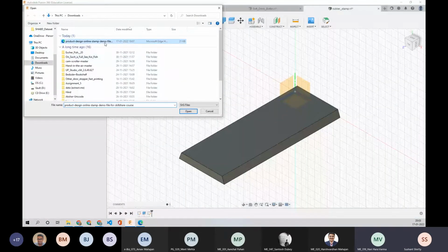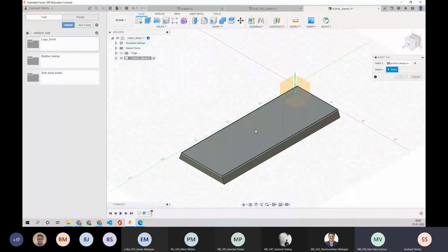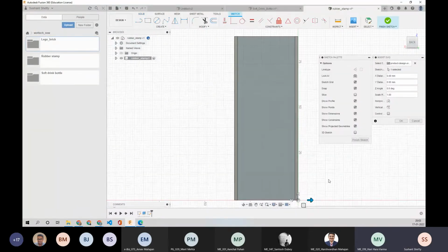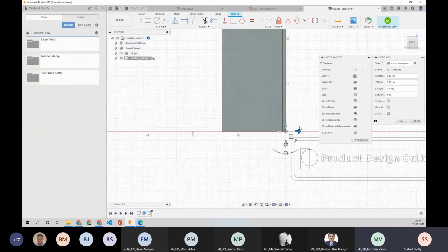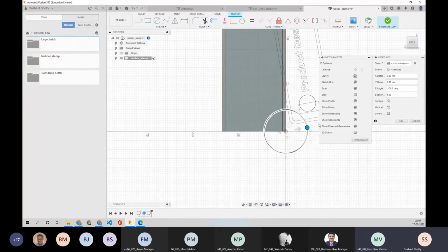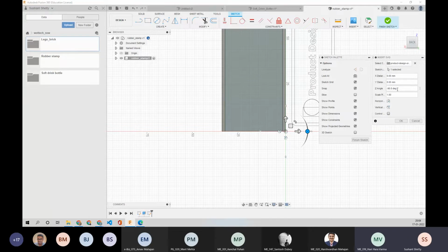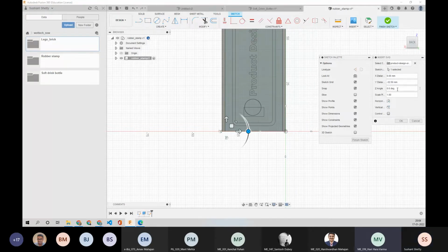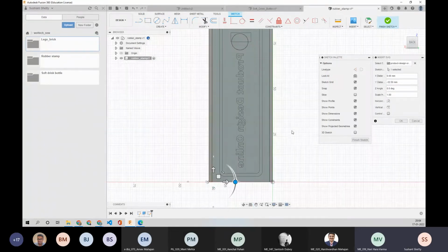So there's this horizontal swap which was there, which I completely missed. Okay, so we'll go back to this again. We'll keep this at 90. We'll keep this at minus 32.5. Come back here, and this is the horizontal flip thing which is there. So if I click on this, now if you imagine, stamping it from the other side, it'll be stamped properly. So we click on OK.